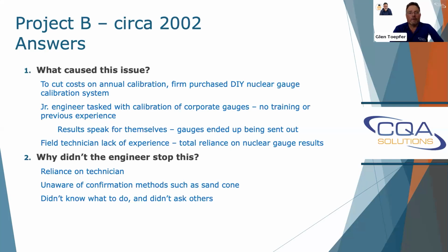How I had figured it out on my own job site was that I was having problems with my gauge, and I ended up doing sand cones and moisture tests and figured out the gauge was wrong, but it wasn't consistently wrong. You couldn't put in any type of offset that would get it to pass a test from one day to another, really from one test to another. And then we found out that they had calibrated the gauges internally.